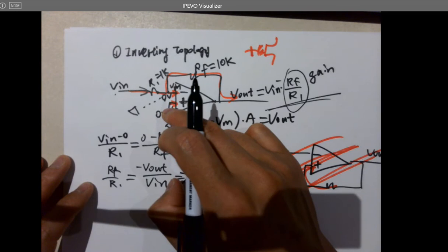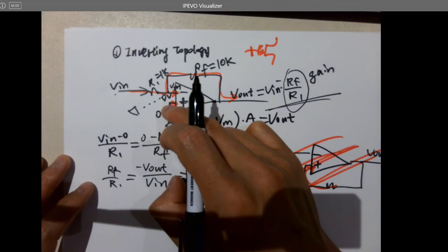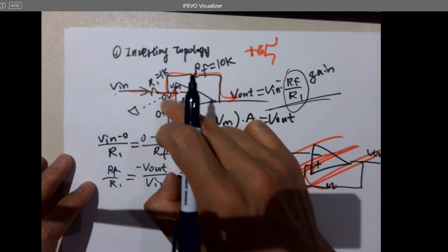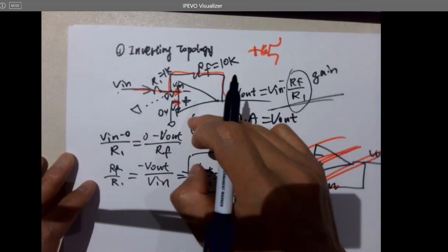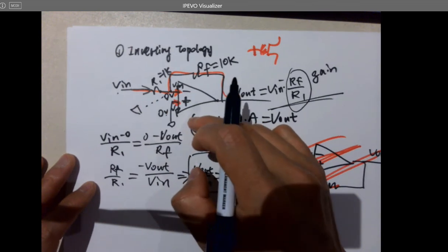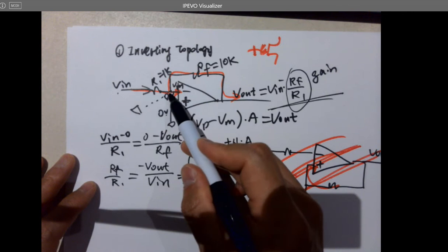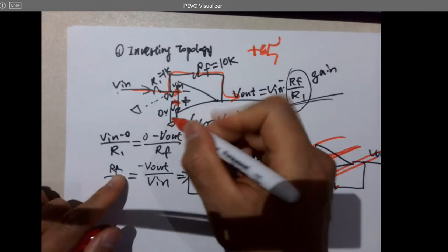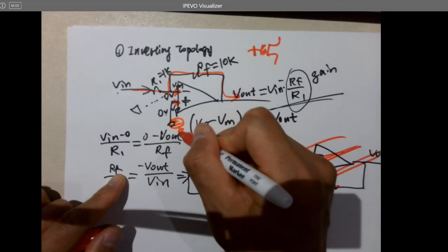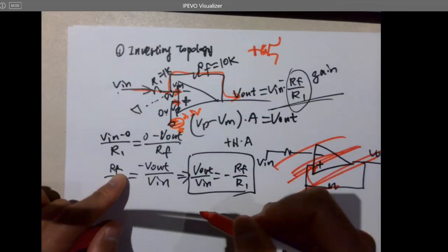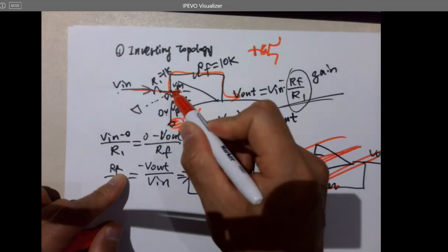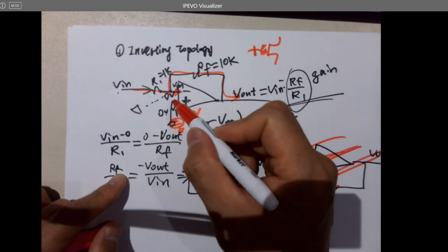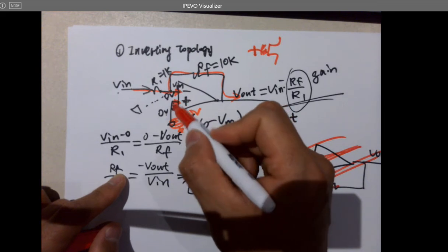It takes a few lectures. So it's not an analog class, right? Just keep in mind, they are equal because of the negative feedback and the huge open loop gain. It's not always virtually shorted to the ground, because this is not always ground. If you have a little DC offset here, like 2.5 volts, what will the voltage here be? 2.5. They're always equal to each other. Remember the negative feedback? It's going to force these two terminals to be the same voltage.